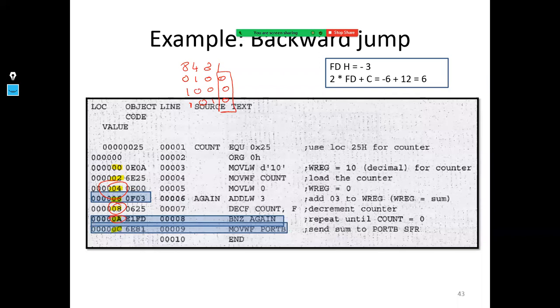Why is the first bit always 0? Because all the addresses are even. Why are the addresses even? Because each instruction can take 2 bytes or 4 bytes. So the number of bytes needed per instruction is even, so all the addresses of the instructions will be even.